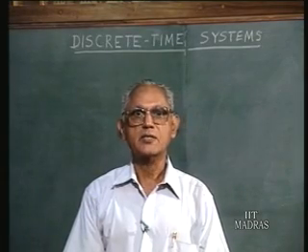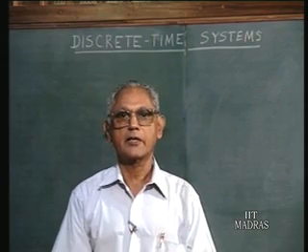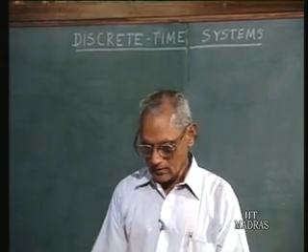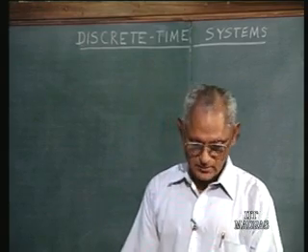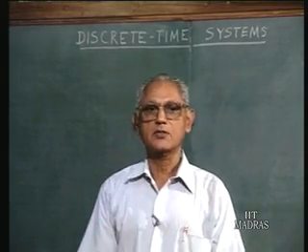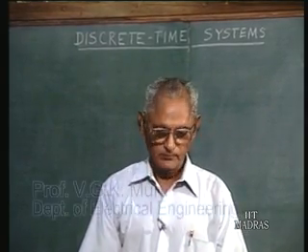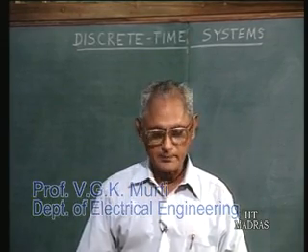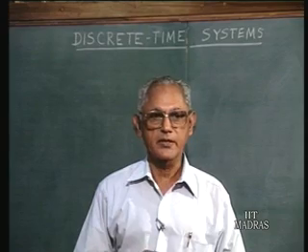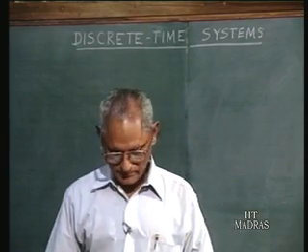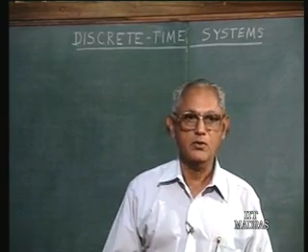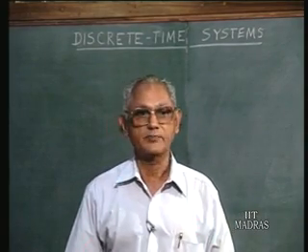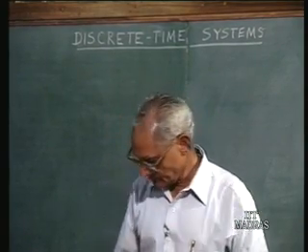We acquainted ourselves with the concept of discrete time system function H(z) in the last lecture. We defined this discrete time system function as the ratio of the z transform of the output discrete time signal to the z transform of the input discrete time signal with 0 initial conditions prior to the application of the input. The definition follows on close lines to the definition of the system function in the continuous time case.